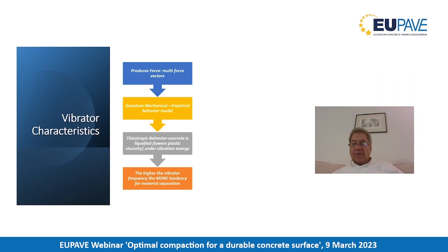The near solid concrete is liquefied, with reduced viscosity, during vibration and returned to a solid once the vibration stops. Vibration is meant to extract micro air, somewhere around a millimeter in diameter, and leaves the concrete in a uniform state that it was placed.